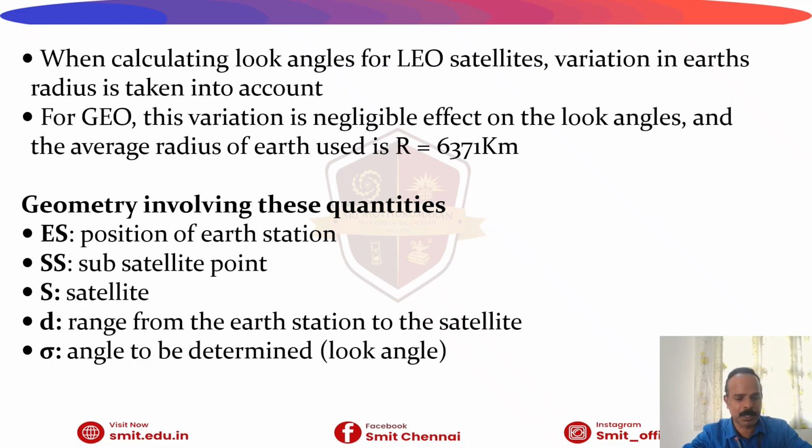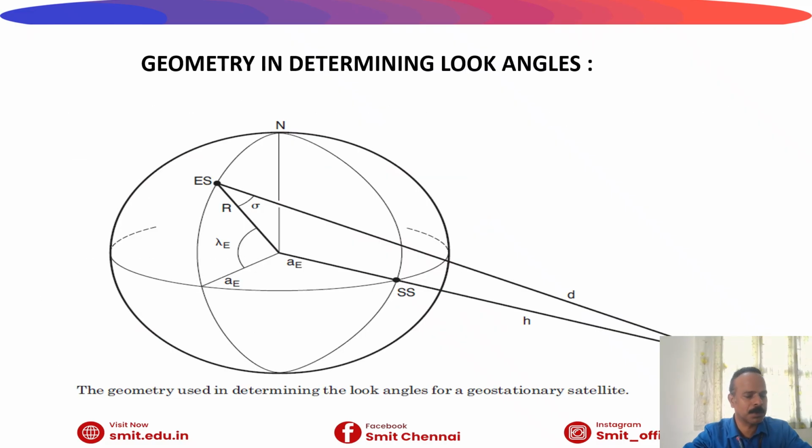Second, the geostationary orbit, which is also called geo orbit. In geostationary orbit, the satellite appears to be stationary relative to the Earth. Therefore, the antenna can be fixed in only one position. There is no need of tracking. So tracking is not at all required in geo. This makes geo satellites very effective and very useful for TV transmission as well as for broadcasting purposes. For example, satellite TV antennas installed in homes do not require any type of tracking.